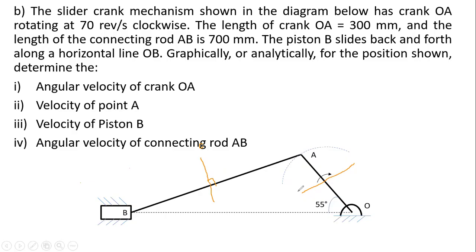Then the very first one to draw, the one you have to start with when coming up with your velocity diagram, is this one whose value has been provided, OA. Here is where I use the scale of 5 centimeters to represent 131 meters per second, respecting this direction, remembering that we're going clockwise. So we transfer it and measure the 5 centimeters from O up to A there.